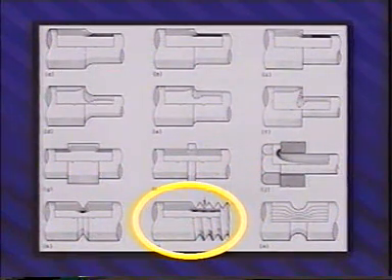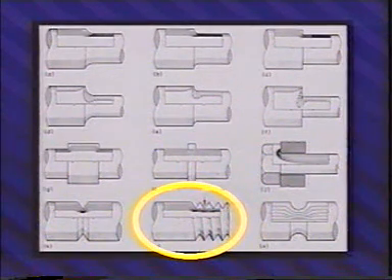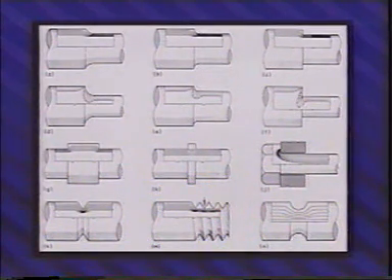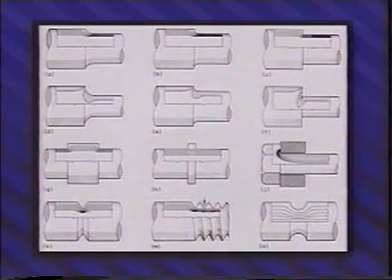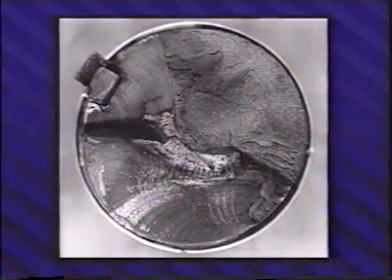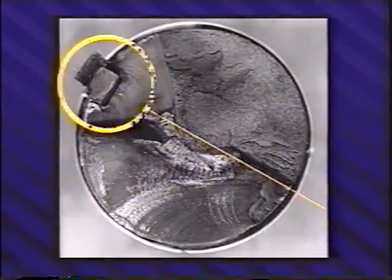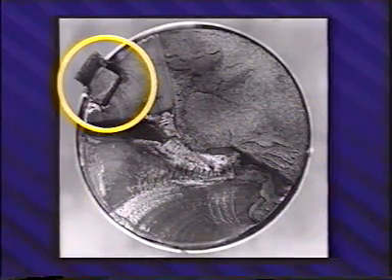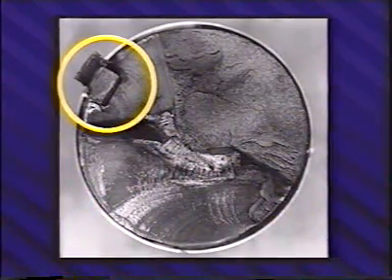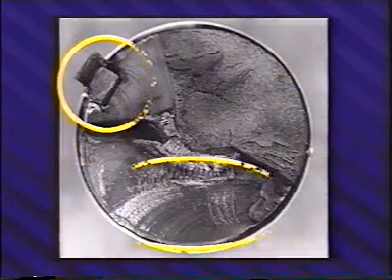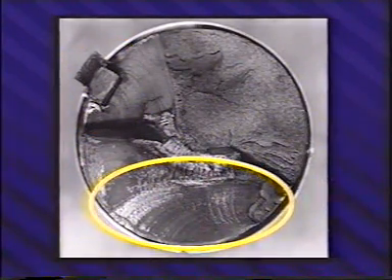The reason is that a continuous thread affords a more even distribution of the stresses on each of the sides created by the thread. That is, each thread is somewhat relieved of stress on both sides of the notch, all except the last thread on the bolt, which is relieved of stress on one side only. Thus, bolts frequently fracture through the first full thread. When a stress is predominantly torsional, the fatigue cracks usually start at the fillets of a keyway. The stress flow at the keyway is distorted by contact with the key, and the maximum torsional stress is concentrated just below the surface. Farther away from the keyway, the stress is smooth.